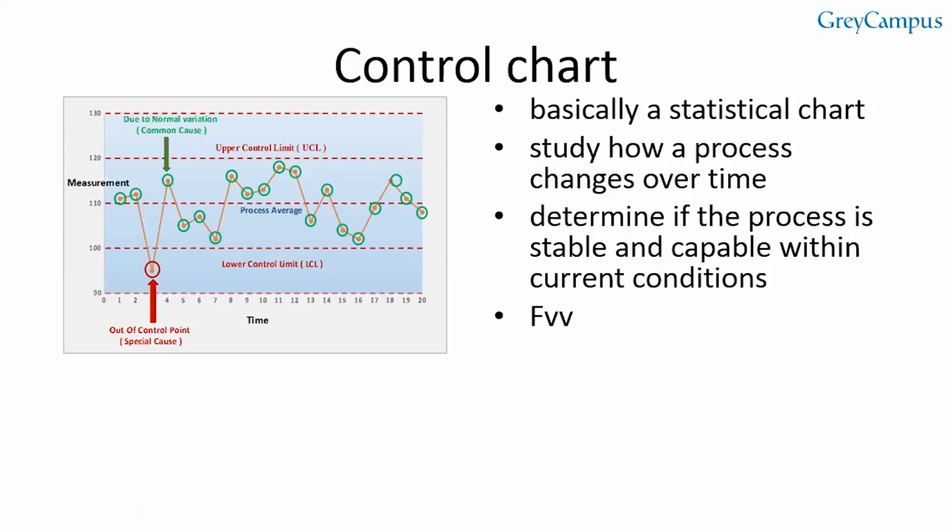The control chart is definitely based on data, absolutely based on data. And it tells how a process is actually performing versus specification limits, which are based on customer requirements. The specification limits tell how a process is desired to perform, but the control chart tells how the process is actually performing. The control chart is used for establishing a measurement baseline. You have to have a baseline to say, what was it when we started, and then what would we like it to be? So the control chart establishes a measurement baseline.